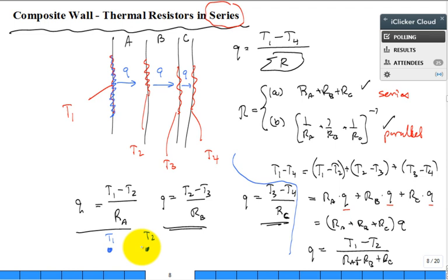The nodes represented places where you had voltage measurements, EMFs, electromotive force measurements. What flowed between the nodes in your electric resistive network through resistors was the current. Here, nodes for a thermal network are representing the temperatures, and here I have 4 temperature nodes for this network. And then we had a resistor between. What flowed through the resistor? My rate of heat transfer. Just like electrical current flows through electric resistors, rate of heat transfer Q flows through thermally resistive resistors. And so I had 3 resistors in series. The sum of each individual resistance gives me the equivalent resistance of the network.